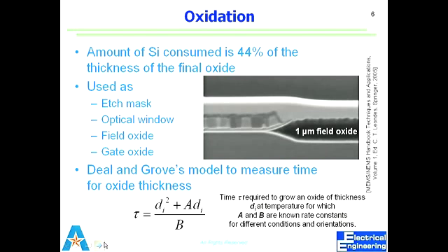What can we say about its interaction with photoresist? What is the ideal requirement for the reaction of BHF with photoresist? It shouldn't react, right? So we call this property selectivity of etch. When we talk about it, we would say BHF is very selective between silicon dioxide and photoresist.